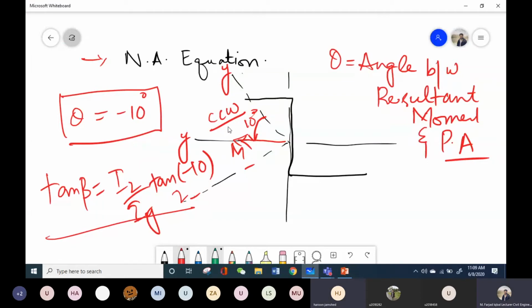Yes. Now, in the case of a symmetrical section, the angle was with the horizontal principal axis. Now, if you see in this figure, I have two principal axes. One is this y dash and the other one is this z dash. So which principal axis is y dash? When I have rotated this horizontal axis into this position, can I say that y dash is my inclined horizontal principal axis? Right? y dash is the orientation of this horizontal y axis. Did you get my point?